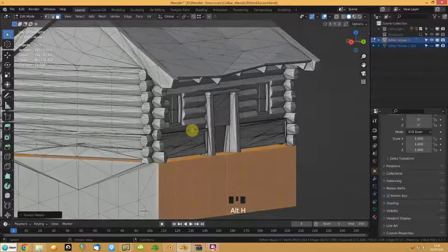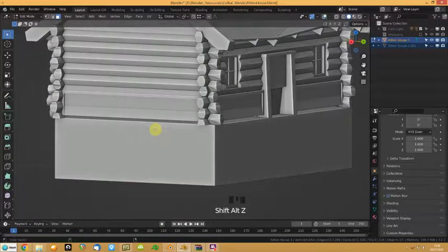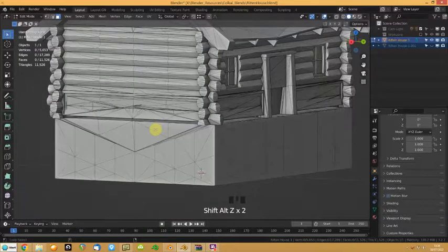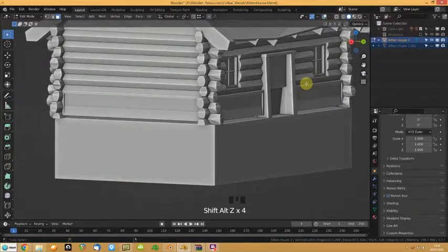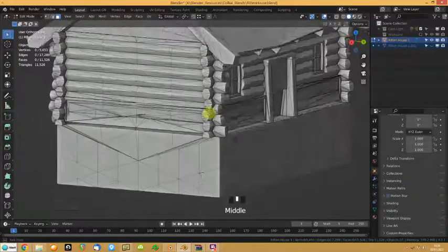And so what you'd be inclined to do is try and tidy this up a bit. I'm using Shift Alt Z there to toggle the overlays. If you look up here, you can see the overlay toggling. Now you see I pressed Shift Alt Z there and nothing's happening. I need to be in the viewport. Be conscious that your keystrokes are based on where your mouse is. So if something weird happens, first things first, check where your mouse is, because you may have called a function you didn't mean to.